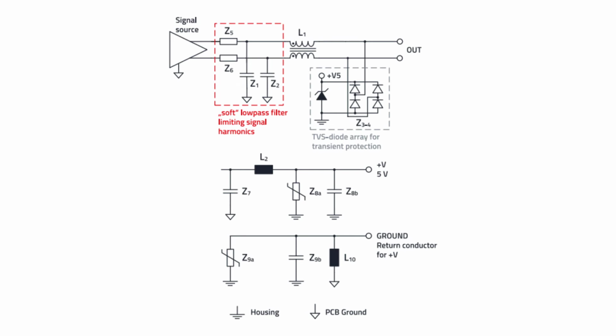Conversely, common mode signals, which are noise components of the signal, are attenuated or dampened by the filter. The TVS diode array provides transient voltage protection, and these spikes are sudden, unwanted bursts of high voltage that can damage electronic components. When a transient overvoltage occurs, the TVS diodes limit the voltage and divert the transient impulse current from the circuit to the ground or the housing.